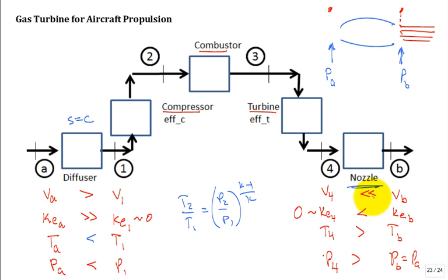How does it do it? Increasing the velocity. So if I said the forward thrust was the difference between the exit velocity and the inlet velocity, that's true. But something else multiplies that term. What do you think it is? Let's take a look at the units. This was newtons, wasn't it? Kilonewtons. What is this? Meters per second.